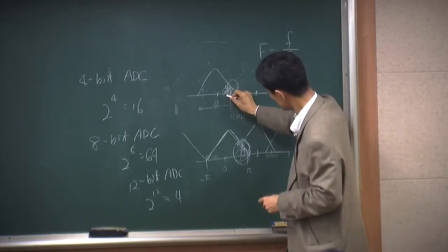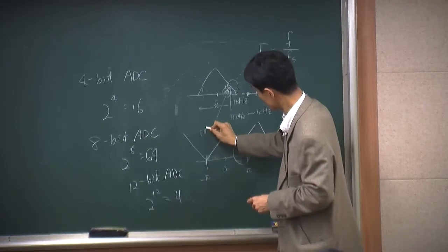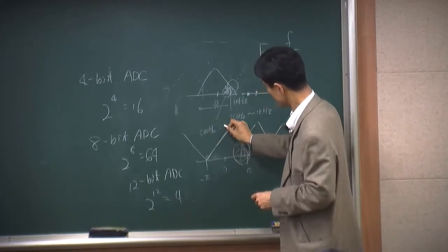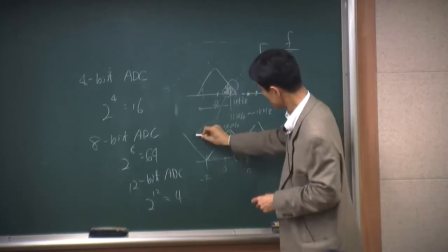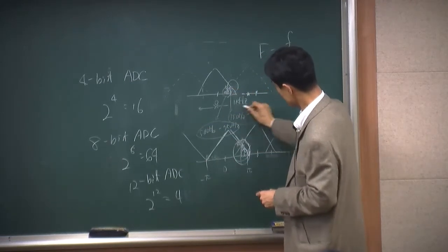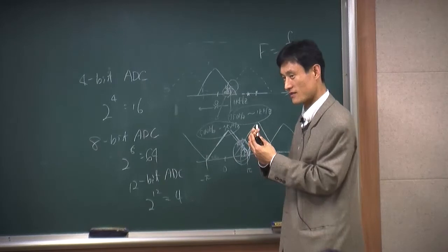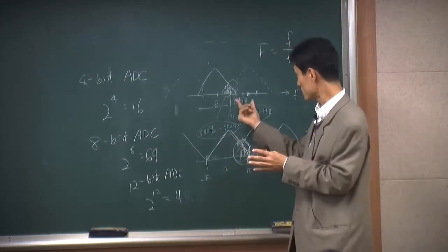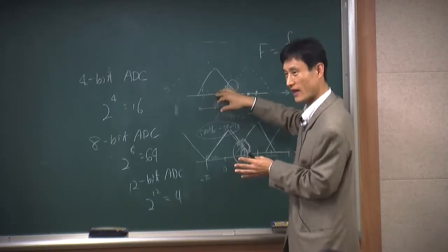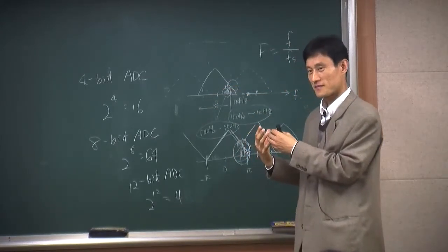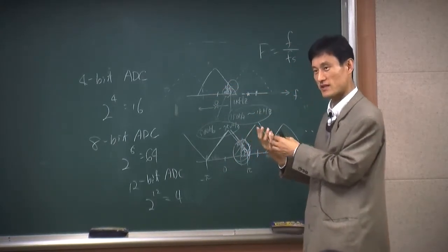So this part was originally 500 hertz to 750 hertz. So your original information of this was frequency, and this frequency is added. Okay, your high frequency component will go back into your own signals, and everything is mixed. Okay, so that's what happened in aliasing.